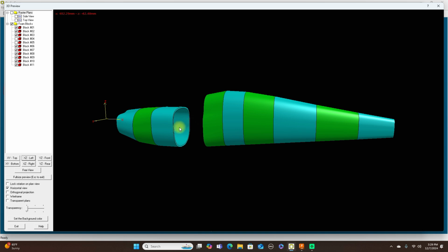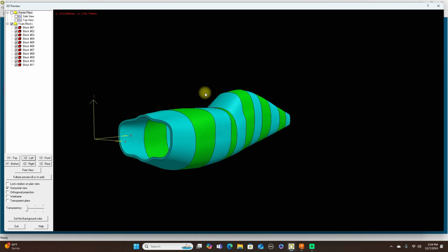You would just do a custom slotting out for the holes. Just use a custom, and then you can use a square, an ellipse, or a circle, and then you can move it to where you want it to be, and then you could put it here, and this would hollow all of this out here and leave all this solid if you wanted to. And the same thing up here if you wanted to cut more out, etc. But this is really good software.